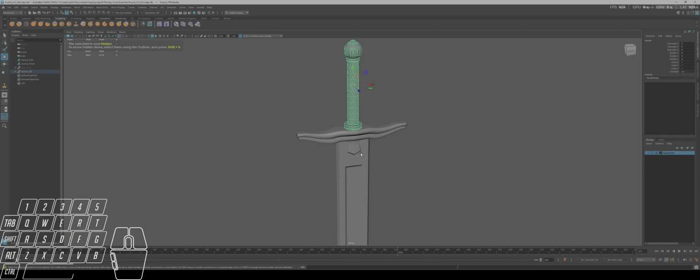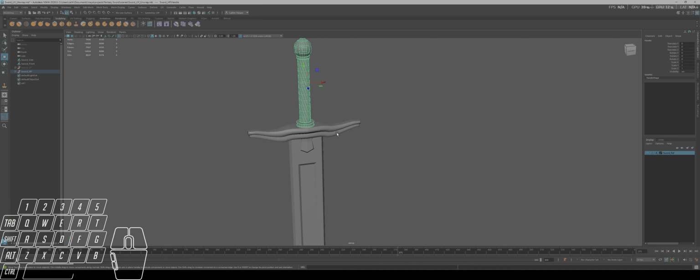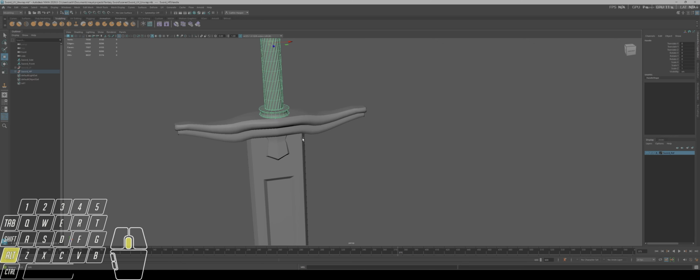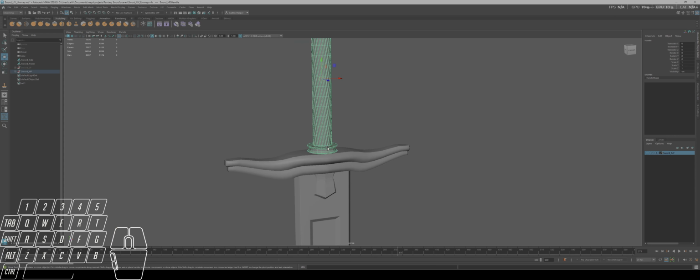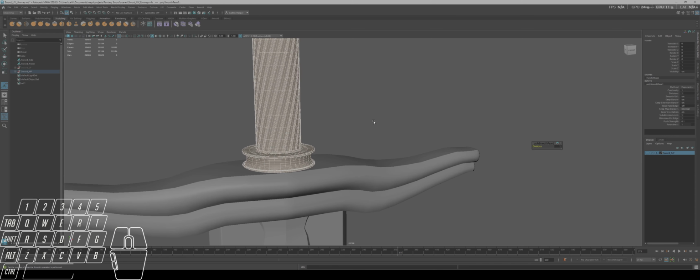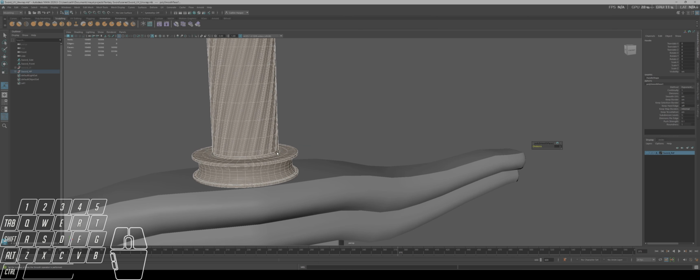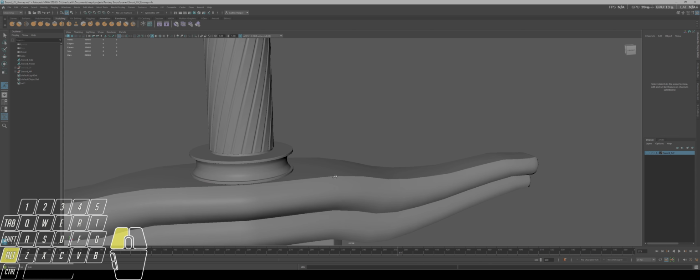With this on our high poly group, we just need to do a few things first, namely we need to increase the subdivision factors. So with that in mind, I'm just going to click my meshes, and I'm going to do these one by one. For my handle, I'm only going to need one subdivision level, so I'm just going to hit smooth, and we're just going to bring it up to 1. That's just going to tighten up all the groupings on our geometry, make everything a little bit cleaner.